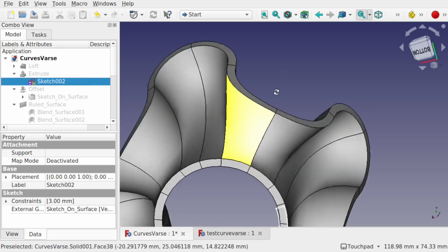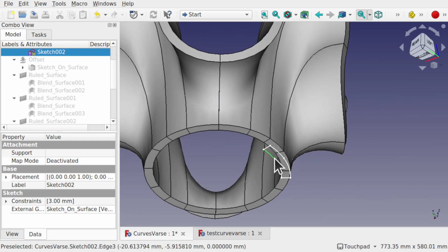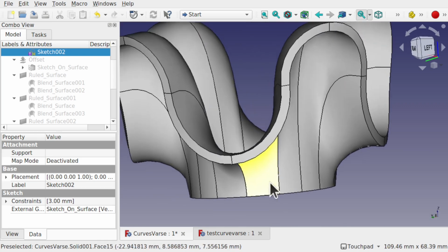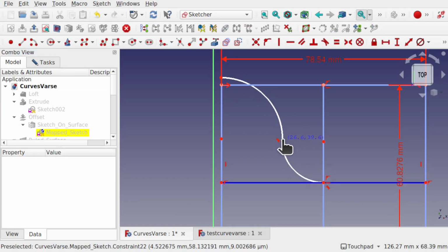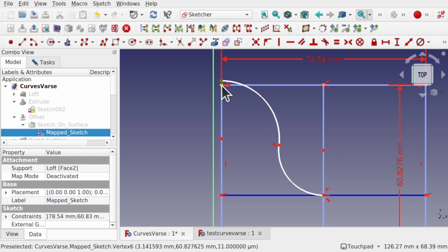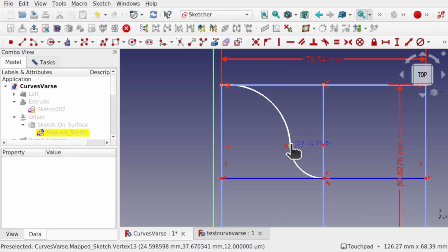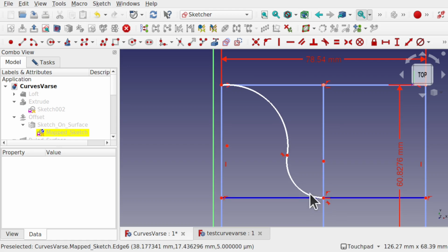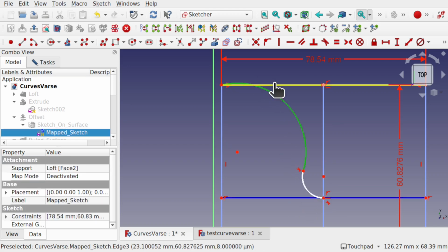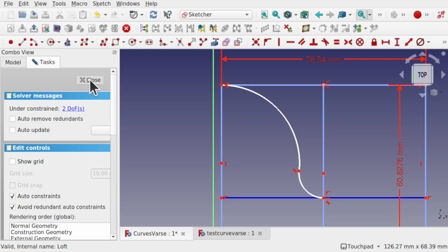And we just let that compute. There we go, that's computed now. You can see that sketch is sitting there. Let's just hide that sketch. And we can take this further. We can even change this curve here. Let's take off the tangency here and attach this point to this one. And we can pull this in and change this to how we want. We have to be careful of the tangency at the top. Let's hit close.